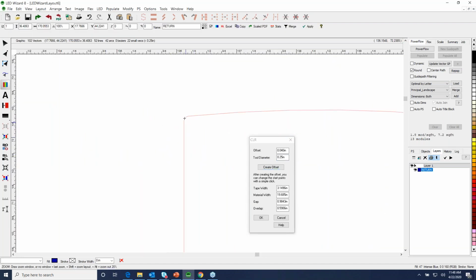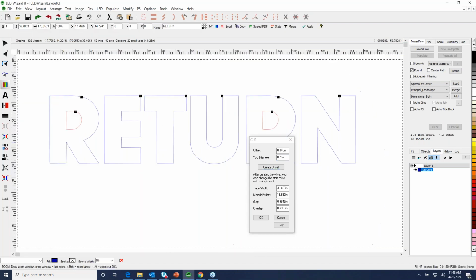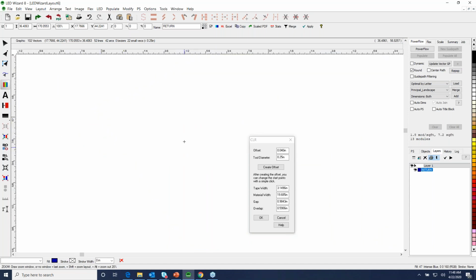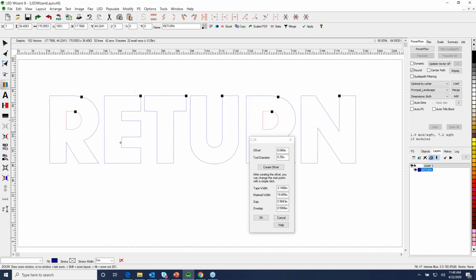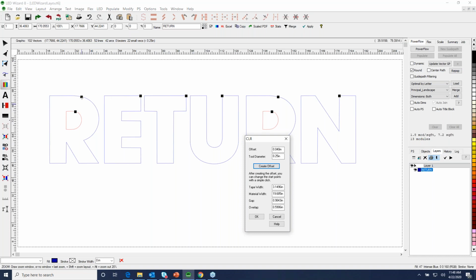If you look close, I've got a little radius on that inside corner, right? It's going to be the same thing here, because that's what my router does, so we want to make sure that that's consistent. Now, these black boxes are the start endpoints. I mentioned that each pattern has a start endpoint, and you have the opportunity here to position these wherever you want.